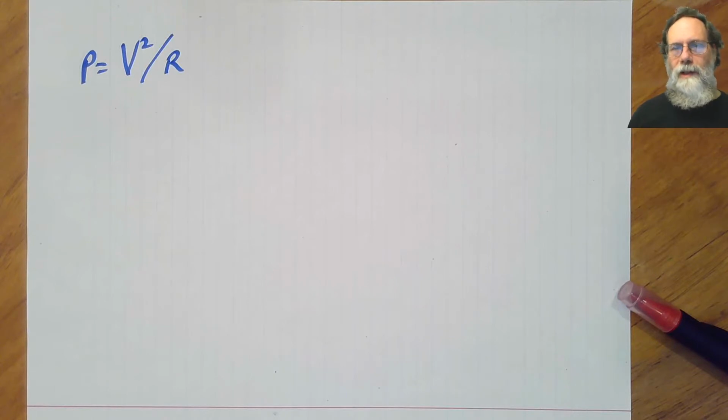There are some limitations, though, because if we wanted a very low resistance in the voice coil of a loudspeaker, we would have to use fairly fat wire. That fairly fat wire is going to have a lot of mass, and that mass is going to cause a fairly low resonant frequency. It's going to make it difficult for the power to actually accelerate the mass of the voice coil, and we're going to end up with an inefficient loudspeaker.